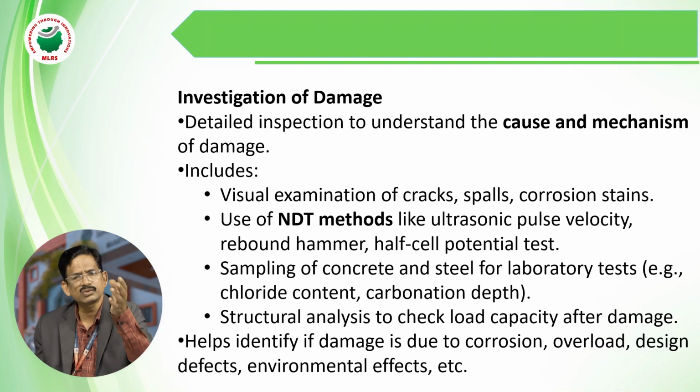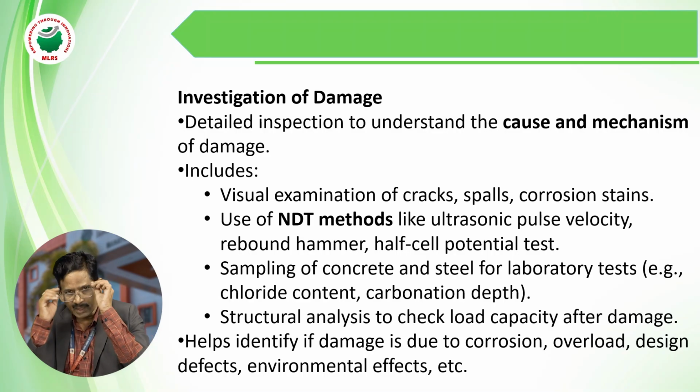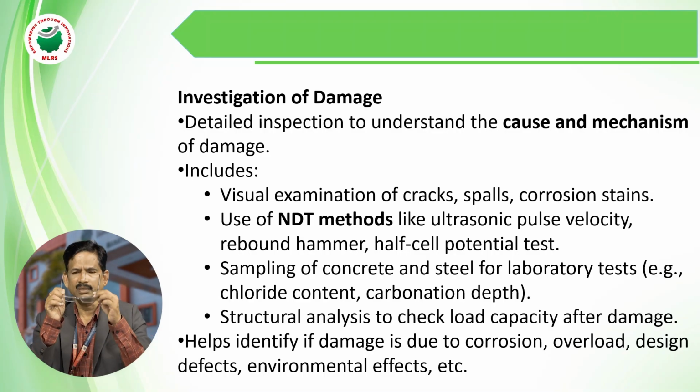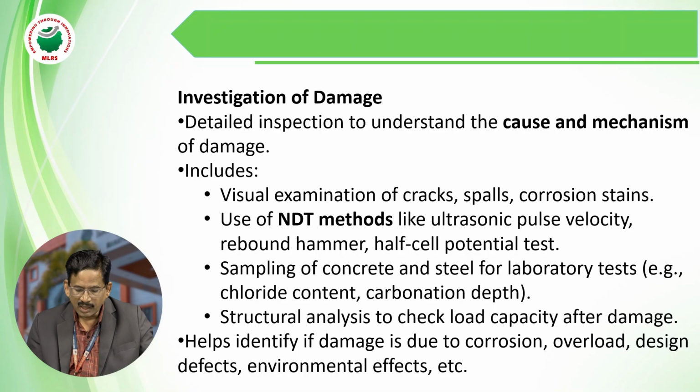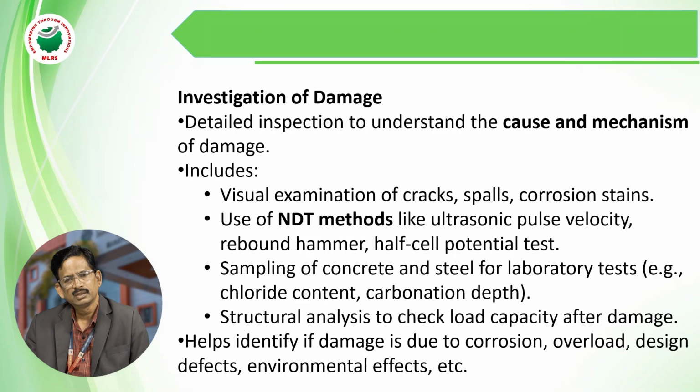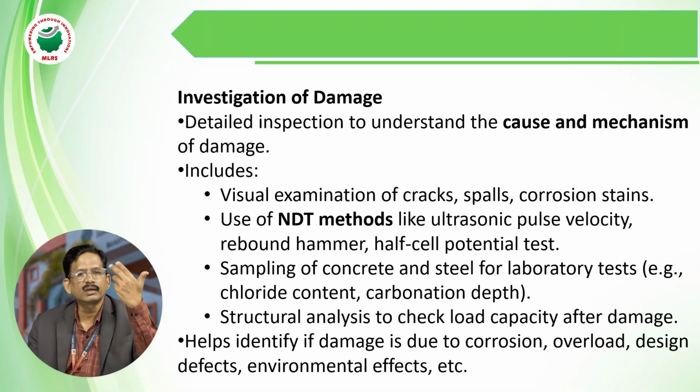The direct method is to see physical cracks with the naked eye. The other is NDT and sampling of concrete and steel for laboratory tests: carbonation test, chloride content, and the rapid chloride permeability test, RCPT. We test that concrete in the laboratory to find how much chloride content is there.